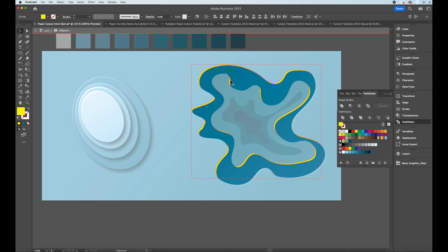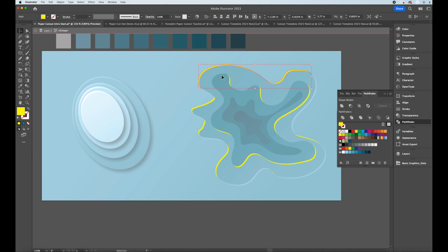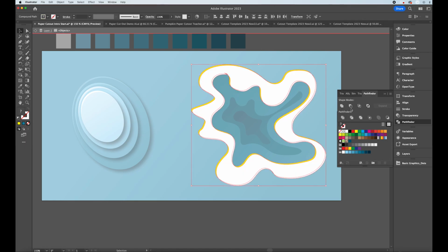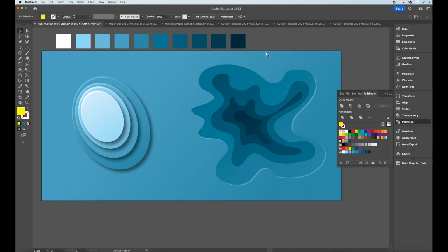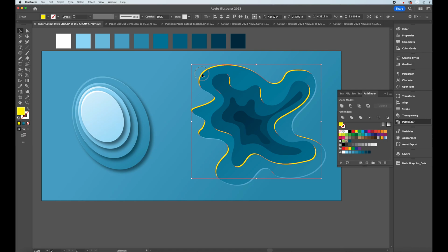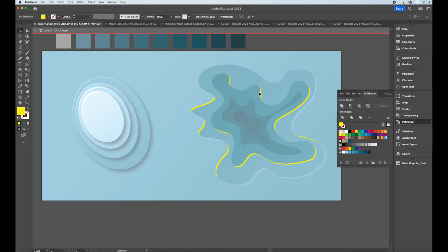Understand that we are going to keep the pieces that appear on the bottom right, but eliminate the pieces on the top left. So if I wanted to go into isolation mode, I could, but it's a little bit easier if we first make a copy, Command C, get out of isolation mode, and then Command F to paste in our features. Again, if I don't want to keep certain aspects, double click, go into isolation mode, backspace out the pieces on the top left sides.